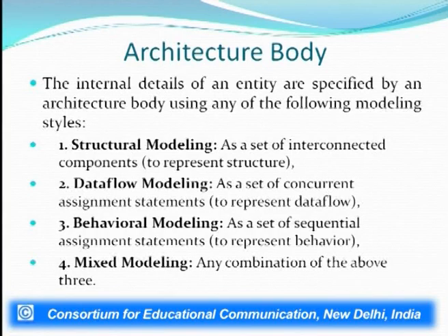The data flow modeling is a set of concurrent statements to represent the flow of data, and the statements will be executed in a concurrent fashion, so they can be written in any order. Then next is the behavioral modeling, which is a set of sequential assignment statements. So, they are going to be representing the behavior and also specifying what is happening after what. So, a sequence is to be followed. Whatever sequence the circuit is going to adopt, the statements in this particular style of modeling have to be written in that particular sequence itself. Then finally, a combination of any of these three can be used, which is known as the mixed modeling style.